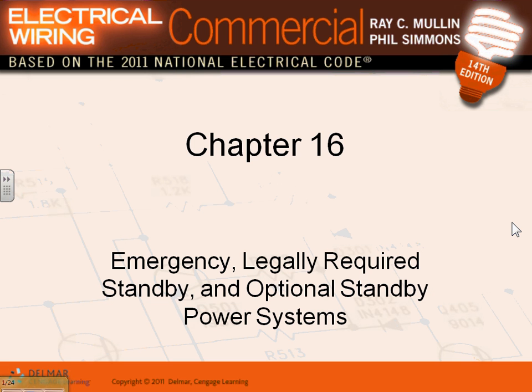And all of us know what the emergency system is, because of the exit signs we put in the building. That's the emergency system. We'll talk a little bit about the legally required standby system. The optional system is up to you. You have a generator to back up the loads, like lights, receptacles, and HVAC equipment. That's your optional standby system.